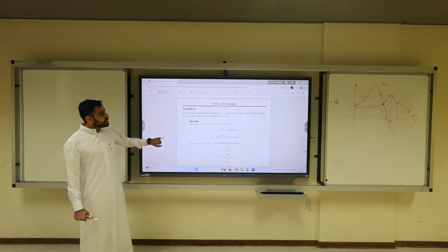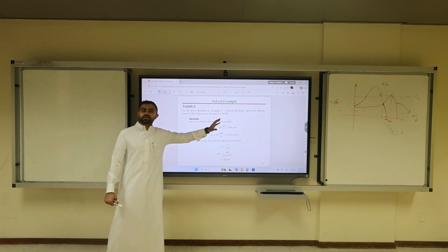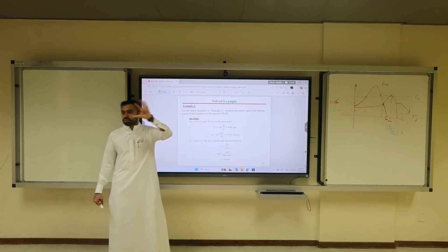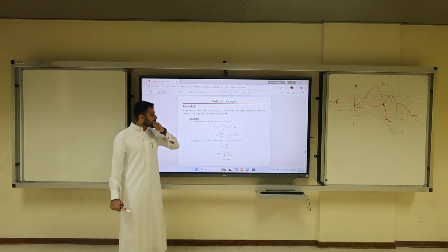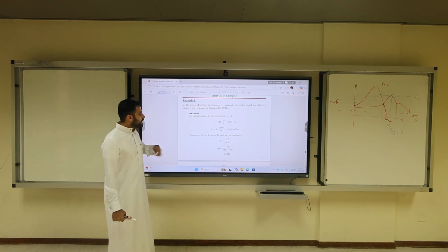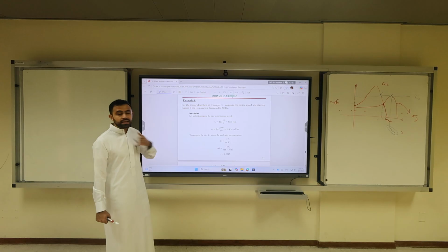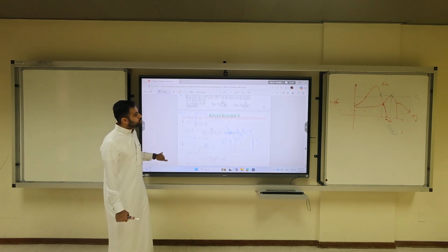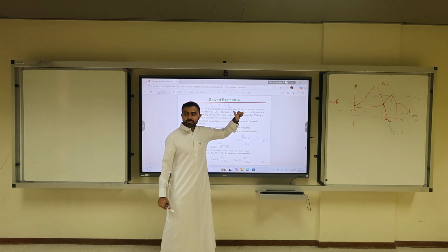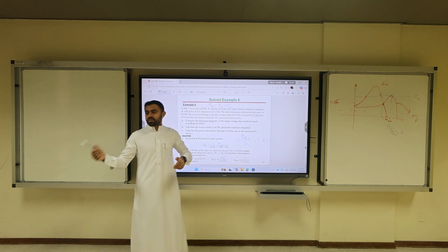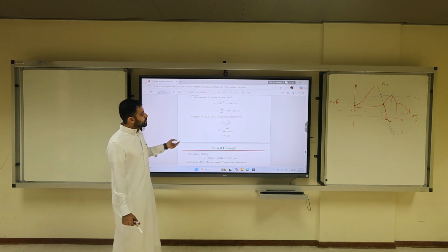Okay? Now, the question asks you to repeat your calculation using 50 Hertz. What will happen if I reduce from 60 to 50 Hertz? I'll have a new synchronous speed, 3000. I'm going to have a new omega S, and we need to calculate the slip. But the problem here is he is not telling you the speed. In example 2, he gave you the speed of 3500 RPM. Now, what is the corresponding speed for 50 Hertz? You have to calculate it using the torque equation.